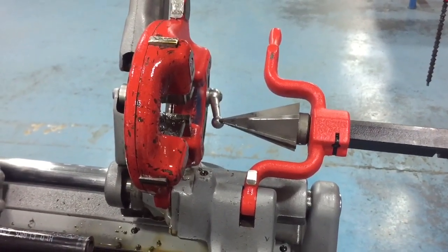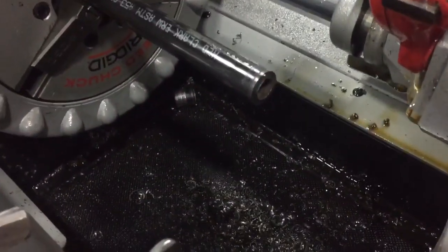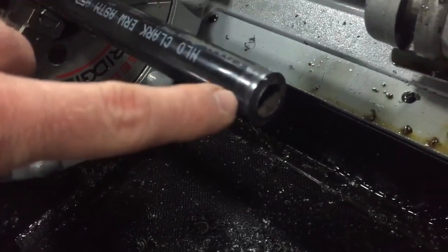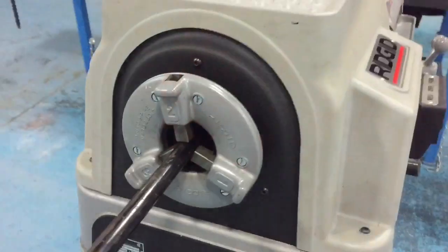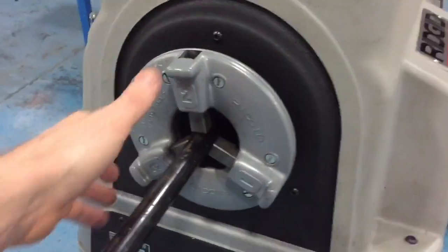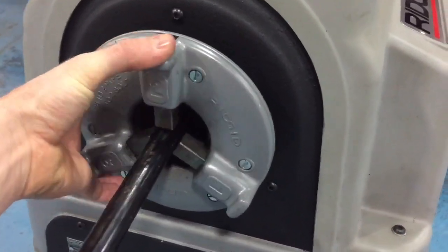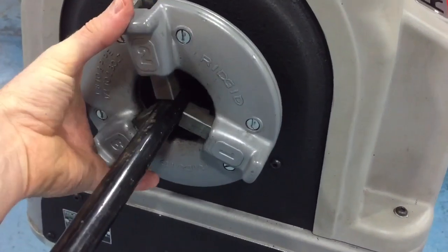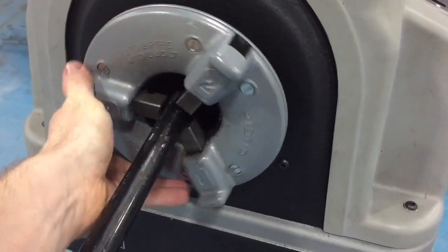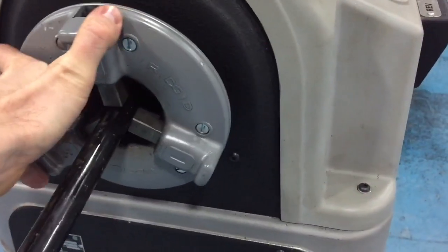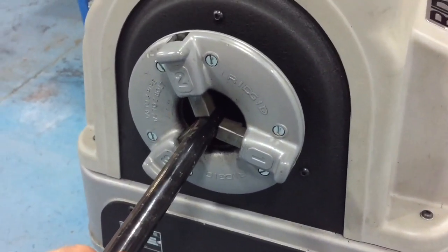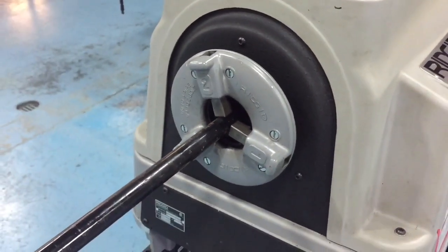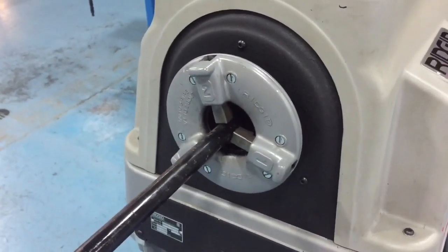So what we'll do first is we've got a piece of pipe in here, it's already been cut. You can see there's some burrs on the pipe, and I'm going to use the reamer to remove those burrs. So on the back side of the threader right here, we also have a chuck or holder to hold the pipe, and just by rotating it, you can see it will then clamp down onto the pipe, so that we're holding it in two points when we're doing the threading. And that way it's not flopping around on the back here.